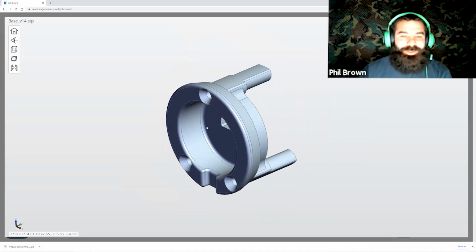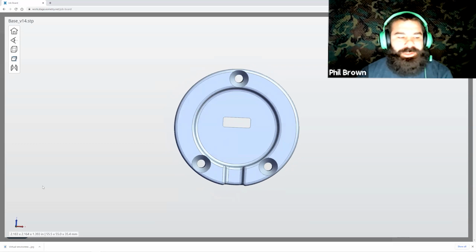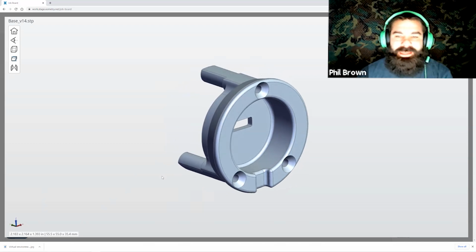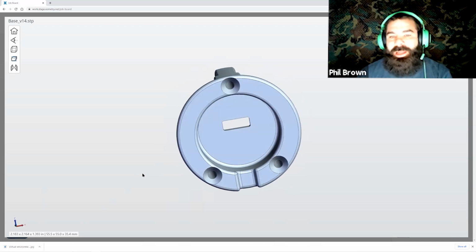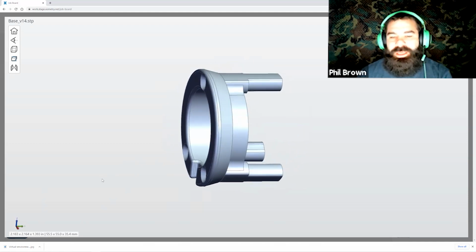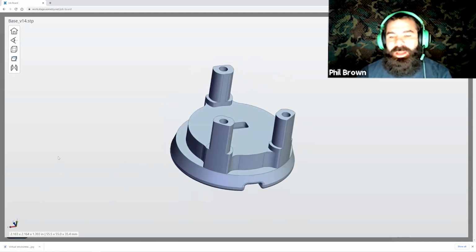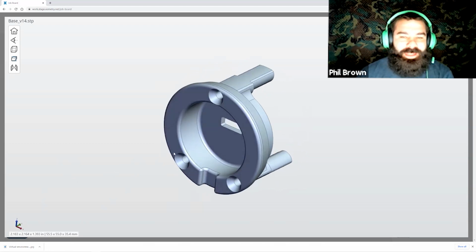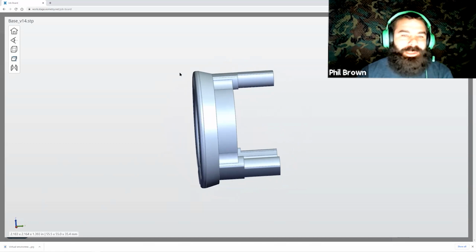Yeah, so jumping into this, the great thing about the 3D viewer is I don't have to download a file yet. I can quickly look at something like this part. In my lower left-hand corner, I can see rough dimensions for stock sizes. I can look around, make sure the backside of the part, as Greg said, is kosher. In this case, I don't have a drawing or a print to work off of, so I don't have to worry about anything hidden. Outside of anything on this part, in my opinion, I would take this part all day long. And from a quick glance, it might be a good strategy to use a lathe. And then if you do have that fancy mill turn, possibly going lathe into mill turn.